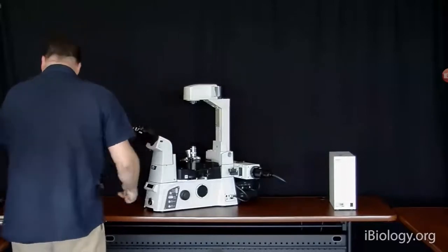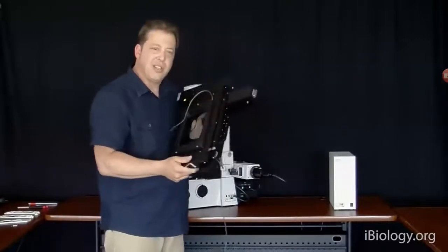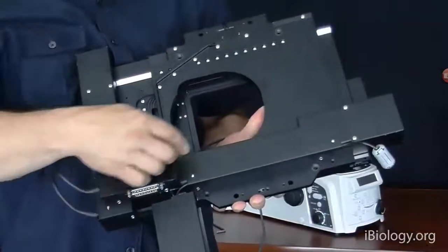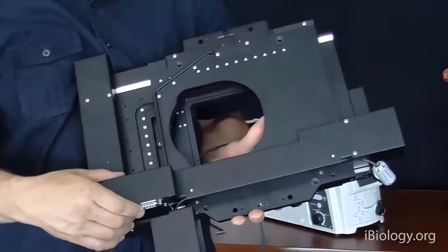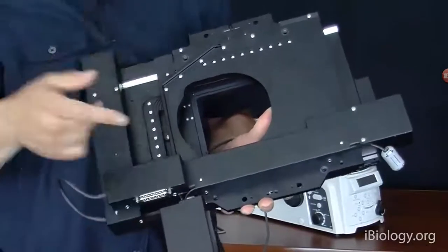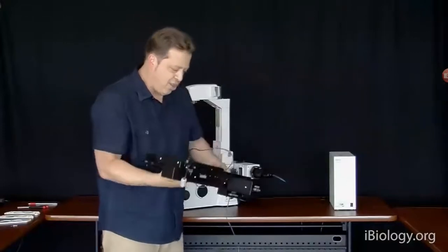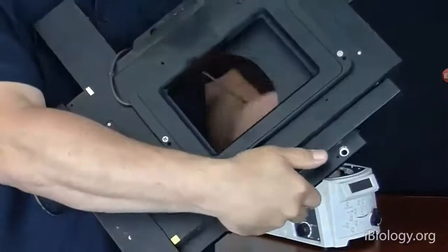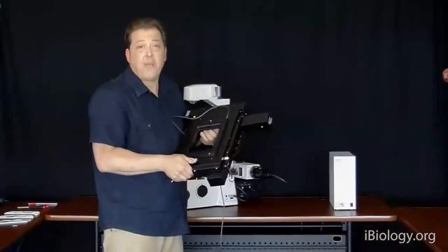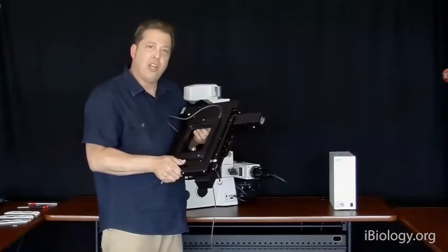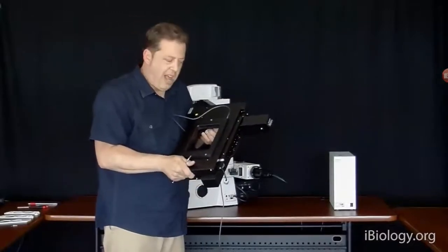So this stage is actually a fairly heavy and rigid component. Basically, the stage is somewhat simple in that it just has lead screws that move the stage in X and in Y. And in this case, it's got encoders, linear encoders that measure very precisely the distance in X and Y the stage moves and reports back to the software the exact position. This stage is also equipped with a piezo device. So this is a piezoelectric device that gives you 200 microns of Z motion that can be very fast, very precise, synchronized for things like confocal imaging, where you want to do extremely fast Z series and move in Z very repeatably, very accurately, as well as very quick.